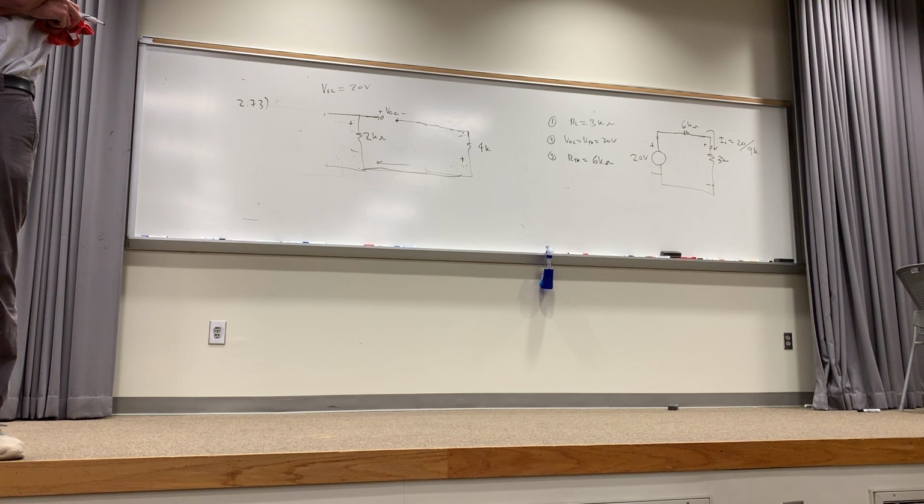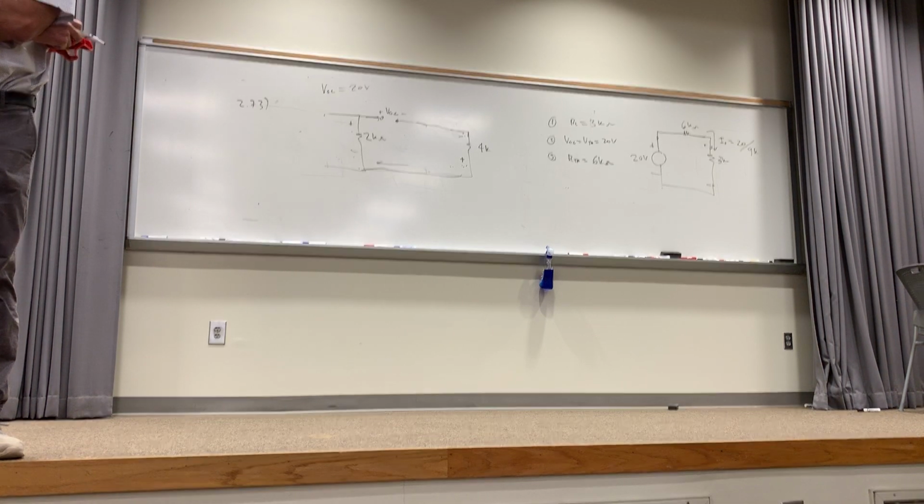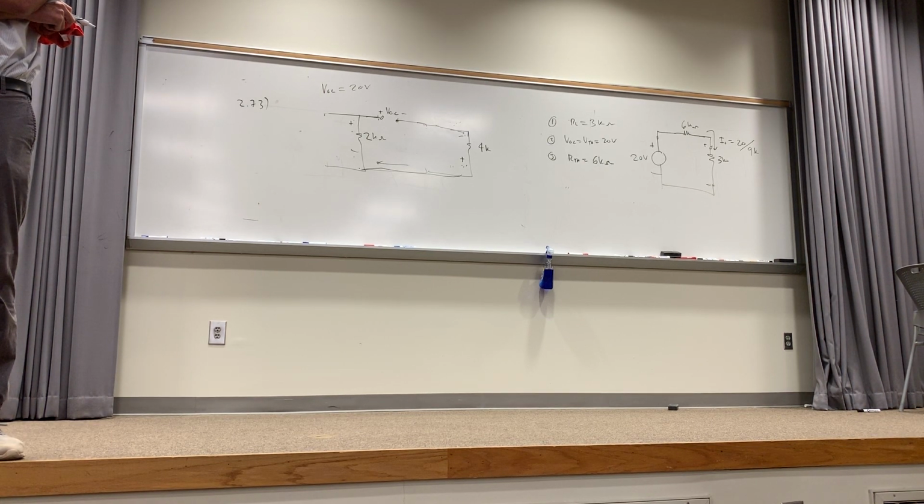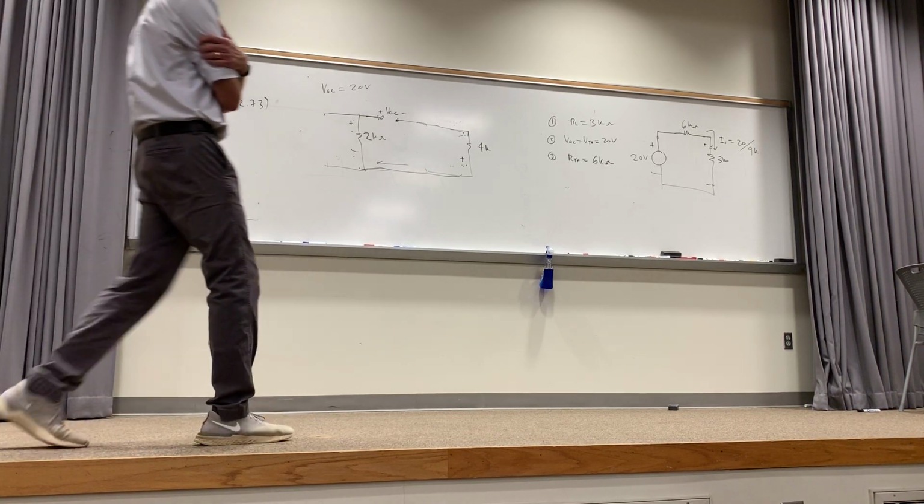But it couldn't flow through that open circuit, could it? So the 6 milliamps was confined to flow through the resistance parallel to it. And the other current was confined to flow through this, there were two 2K resistors in series with that, do you remember? All right, so by pulling that load out, it prevented any current from circulating around from the 2 milliamp source through to the other side, if that makes sense. Y'all understand what I'm saying there? Okay, I see now. I was thinking that the bottom wire was connected. It is, but there's no way current getting on there can get back, so it doesn't go there. You gotta have a closed loop.